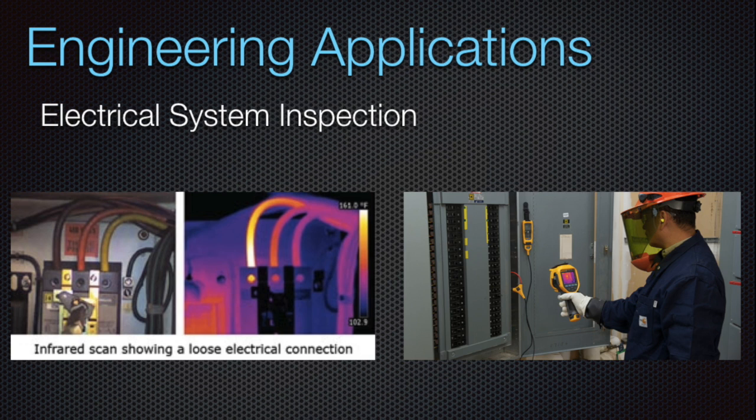the roof. In electrical engineering, there is a strong correlation between the overheating of a component and its eventual failure. As a result, infrared thermography can be used to detect overheating of certain electrical components to prevent circuit failure. In this specific example, we see that in the thermal image produced by the infrared camera, one wire has a significantly brighter color than the others. This indicates that there is a wiring connection issue somewhere in the circuit that is causing overheating and that can potentially lead to system failure if not properly addressed.